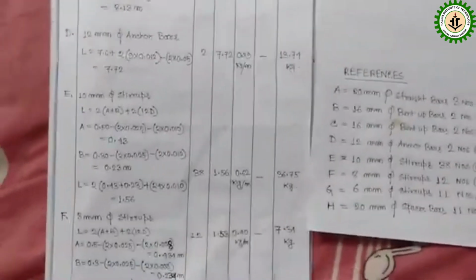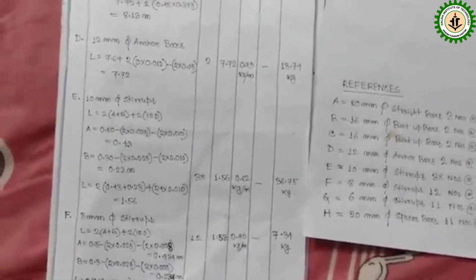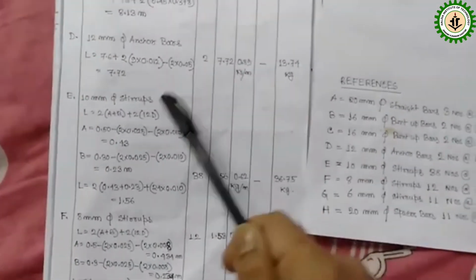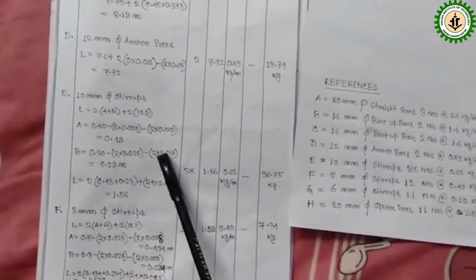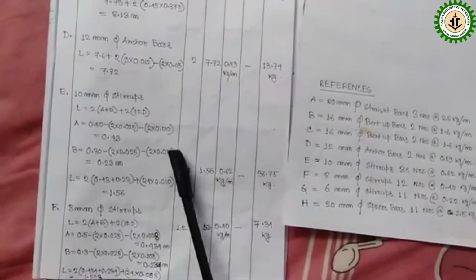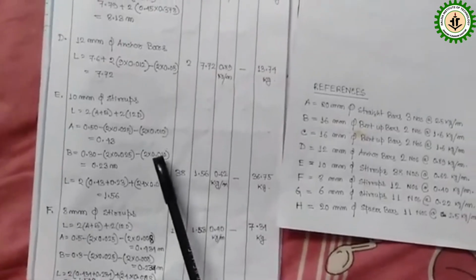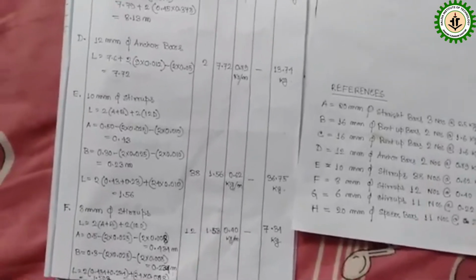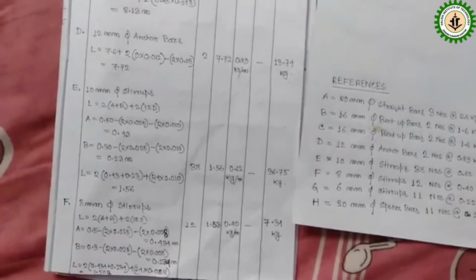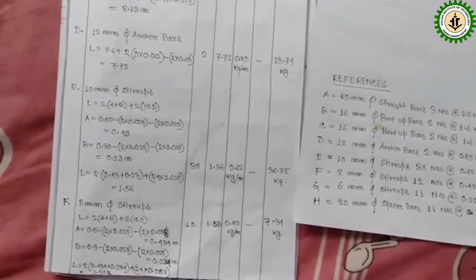So the length of B will be 0.30 minus 2 into 0.025, that is for cover area, minus 2 into 0.010, that is for the diameter of the stirrup. So the length of B, after calculation, is coming 0.23